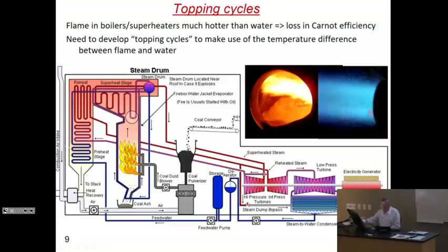And of course, the hottest part of the boiler is the superheat stage. So that's this famous point number 1, which can be supercritical, so 520, 550. The non-critical ones are 480 or so degrees centigrade. But still, that is a very, very large distance in Kelvin away from the temperature of the flames.